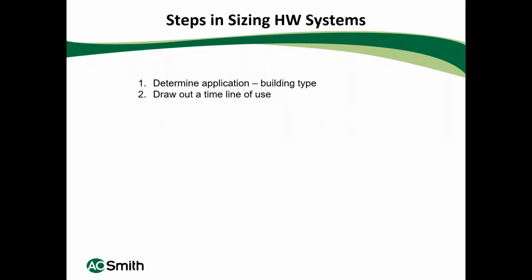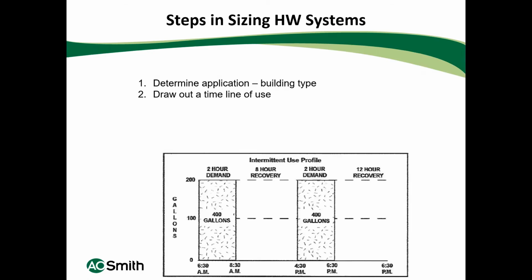It is sometimes a good idea to draw out a timeline of use of your water. For example, maybe a Zamboni fill at a hockey arena. They want to put water in the Zamboni as quick as they can, but that Zamboni might be back 40 minutes later to refill because they have another rink to do. So we need to rebuild that tank within less than 40 minutes. Drawing the timeline will definitely help figure out what size equipment you need.